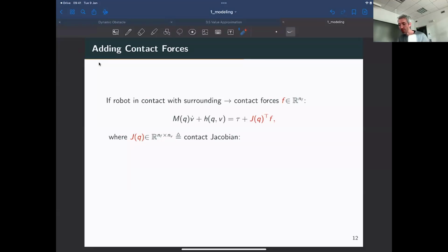This is important when we are talking about legged robots, because if you have a biped where you have a foot which is maybe a rectangular foot, then that biped is going to apply a 6-dimensional force on the ground, because you have both the force and the moment. If you're using a quadruped, the feet are point-like, so they're very small.